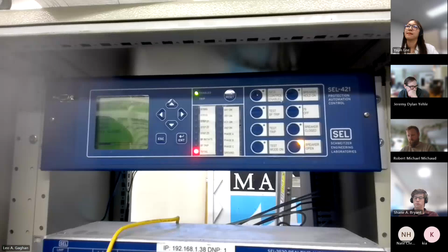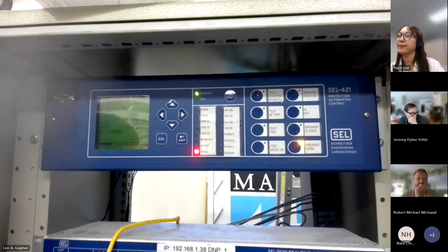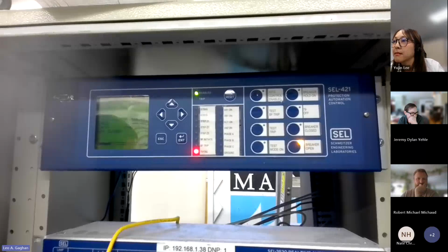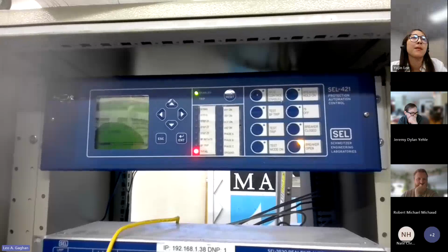So yeah, that's that. We'll try it out here, see how it goes. So what we should see is we press the push button. We should see push button 2 come on, as long as we're in test mode. And then also we should see the trips come on. I don't think we're going to see that breaker change state. It really depends on the timing there.